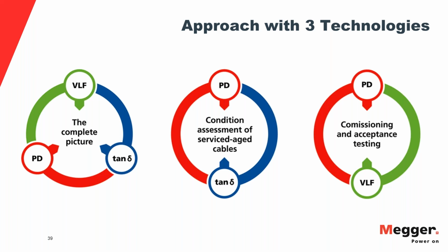So the world is in this case much easier when it comes to IEC, because it's always U0. Whatever you do, you calculate your operating voltage, what is supposed to be, and then you take a multiple of this. This is why it's very easy. You don't need a big table to do that, like in IEEE. But yes, the answer might be different in IEEE because you are allowed to deviate.